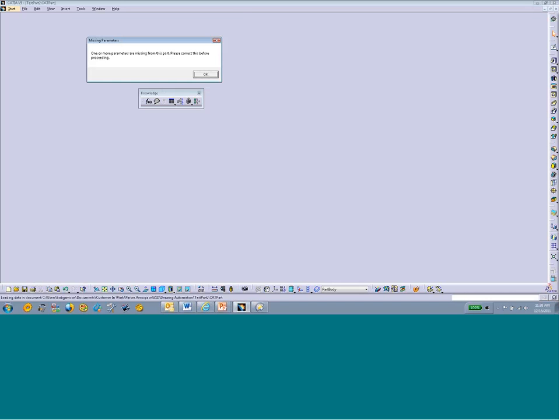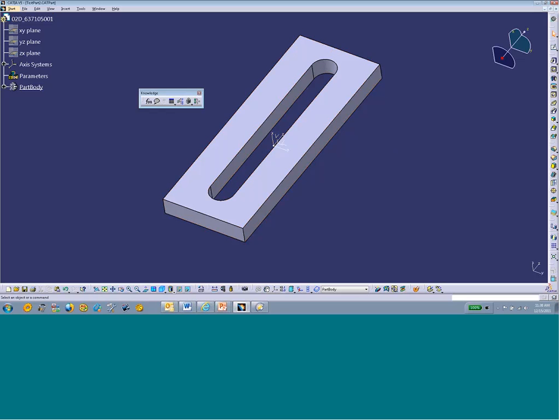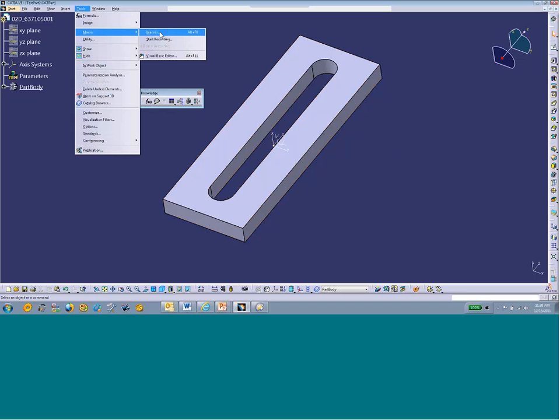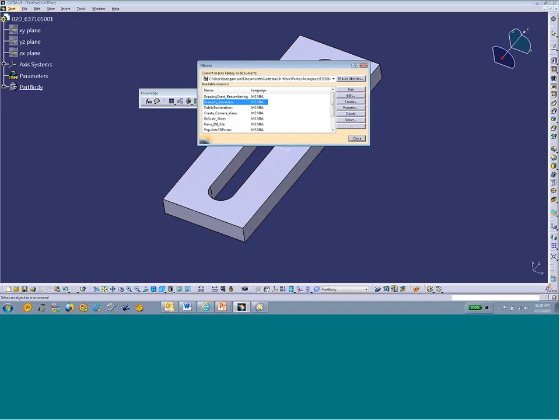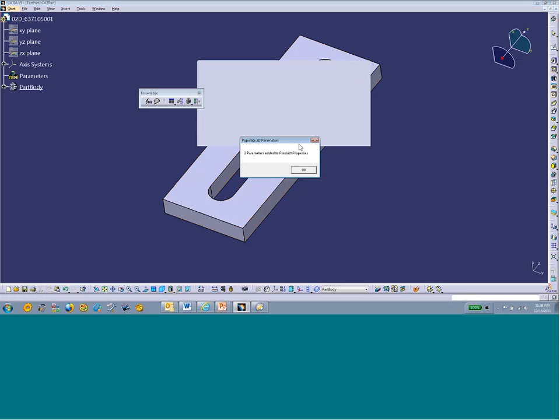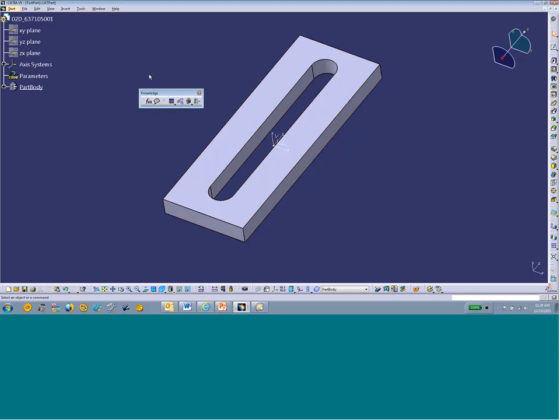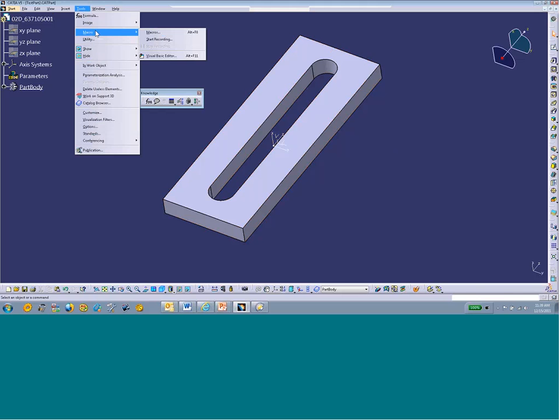And now I'm not seeing CATIA. So let me click OK here. All right, now we're back to CATIA. So you saw that little message that came up. So obviously, at this point, if I come into my macros, what I need to do is populate my 3D parms in here. So we'll run that again, and this time, since 2 of them were already present, it just tells me it added 2 more to the mix. Okay, so now we'll go and run the drawing generator.